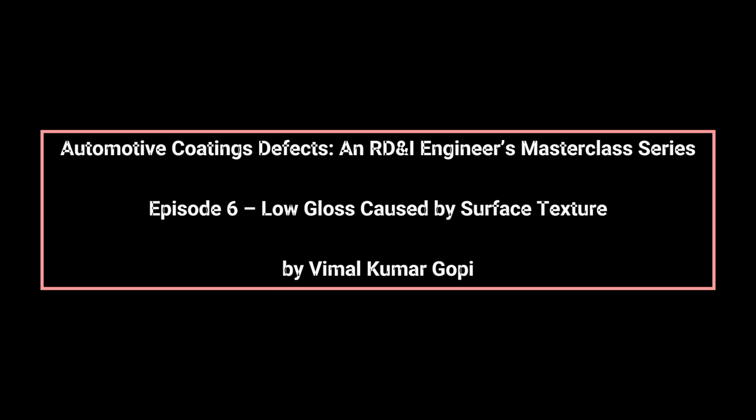From a troubleshooting standpoint, low gloss should always trigger a surface texture diagnosis before any formulation changes are considered. Side light inspection, wave scan data, and tactile assessment provide immediate insight into whether the gloss loss originates from flow, spray, or overspray mechanisms. Once the texture source is identified, corrective actions become clear. Leveling-related gloss loss points toward viscosity, solvent balance, flash off, and temperature control. Spray mechanics-related gloss loss points toward gun setup, spray distance, overlap, airflow, and robot path optimization.